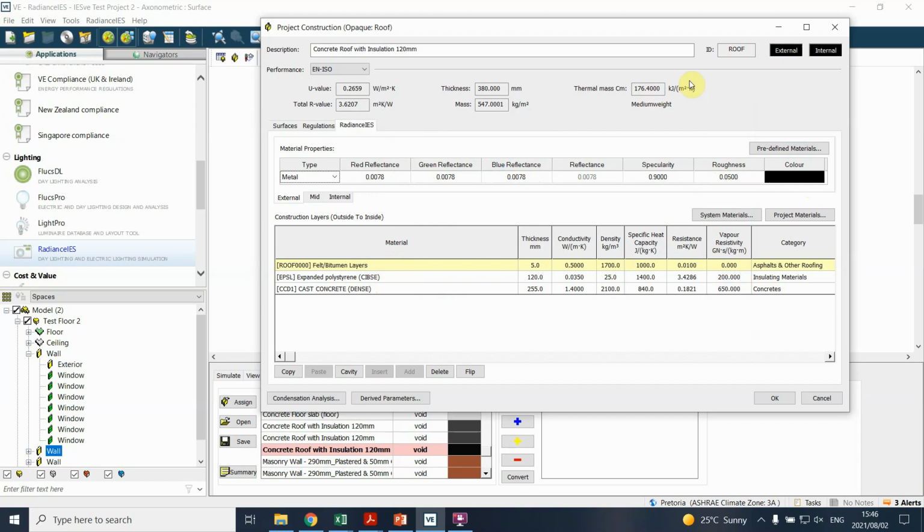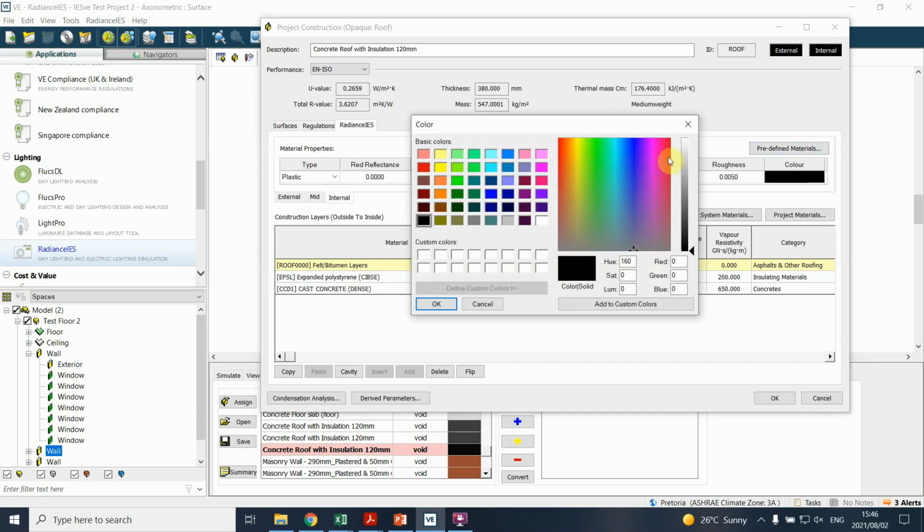This will certainly have an impact in your sun cast analysis and so forth. So you're welcome to explore the use of color in your models. We're looking here specifically at the internal experience or the internal light quality. So we will not use external, we'll use the internal tab there at the top. And if you click again, you can use a predefined material, or you can then say, okay, wait a minute,